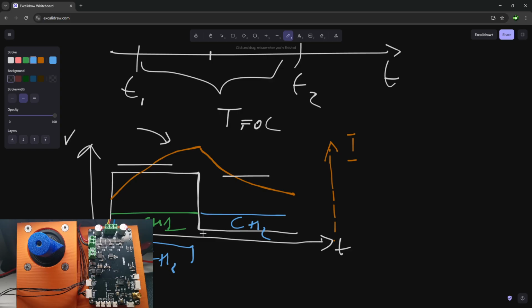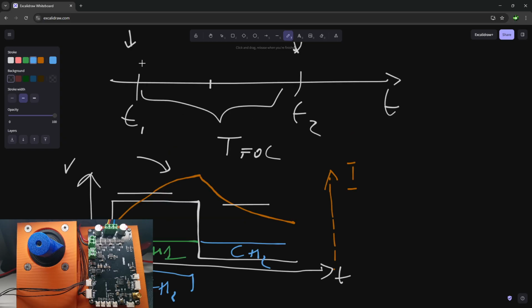And even more, we better measure for as long a period as we can. If we can measure the whole period, we will get a very good average value for this period for every channel. So that's why I personally believe, and I think it's very good reasoning, at least if my explanation was clear enough, that it is better to use separate ADC peripherals for different channels.